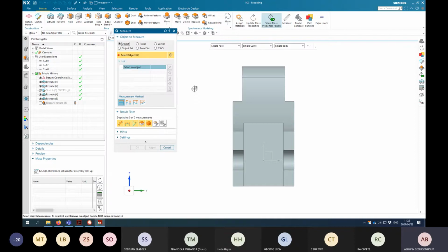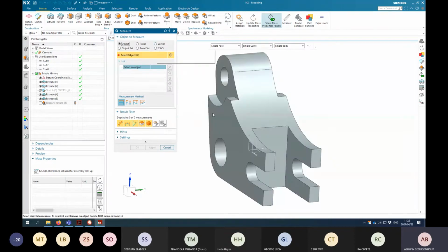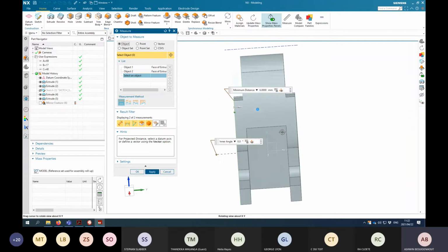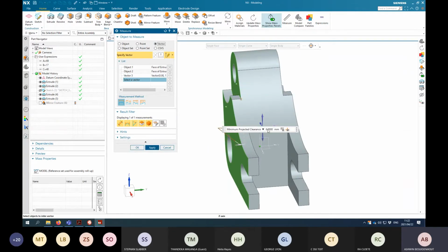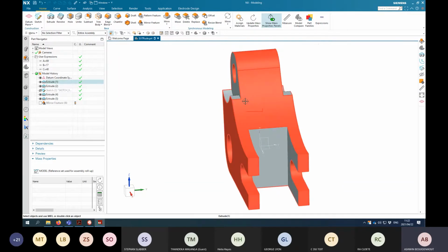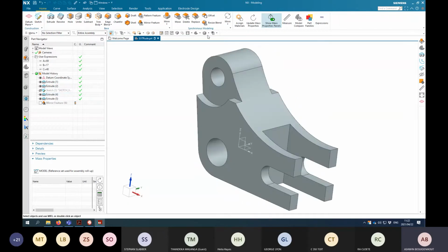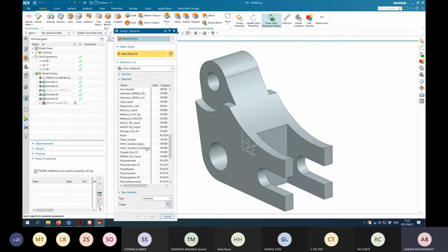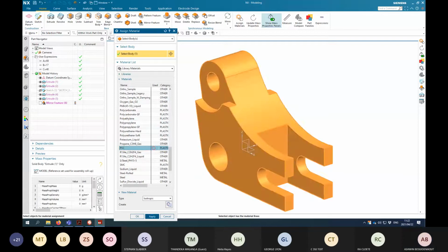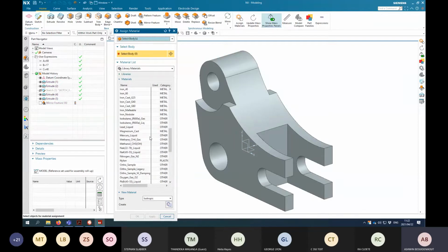So if you take our measure tool, measure this and that, minimum distance, vector in this direction, there we can see that it is 6. So that stays constant. It's not necessary to put in planes and stuff, because that 6 depth is governed by the extrude itself. So now I know that everything is fine. Don't forget, change the value back to PVC. Okay, apply. Let's see. Okay, we can see that it has been delinked in our values, PVC, so that's okay.